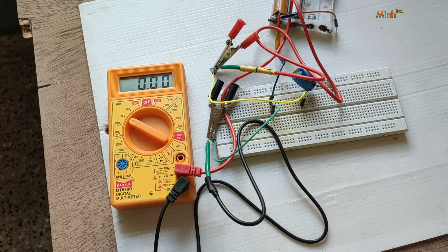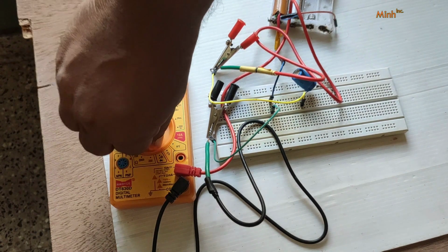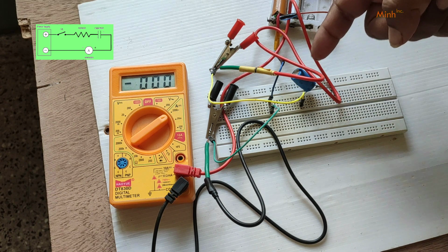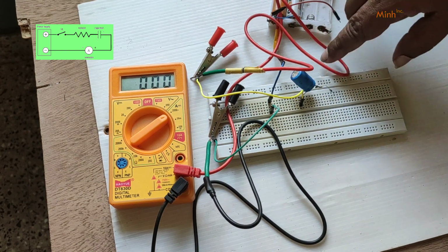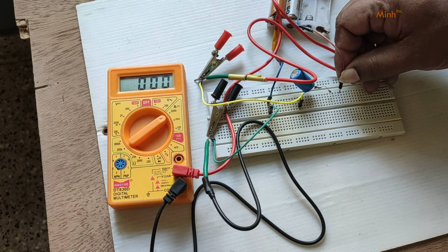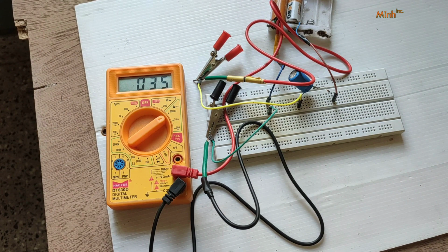Okay, so we have made the connection. Now it is ammeter based, so we'll set it to the microampere range, and the ammeter is connected with the negative of the battery, and the positive of the ammeter is connected with the capacitor, as per the diagram. Now the positive of the battery will connect here, and we'll see the measurement in the ammeter. Okay, it started with 41, and we can see that initially it was very sharp, and the current is decreasing. Initially the current was 41 microampere.